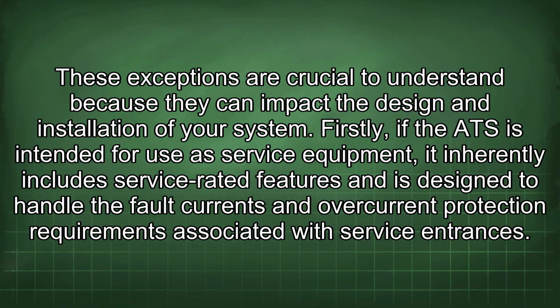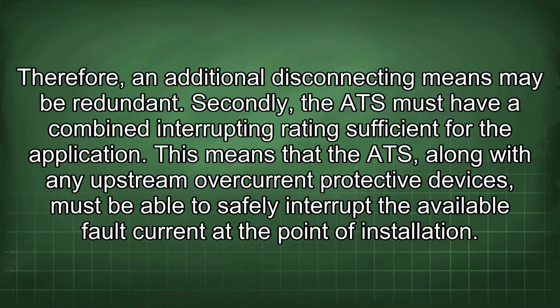Firstly, if the ATS is intended for use as service equipment, it inherently includes service-rated features and is designed to handle the fault currents and overcurrent protection requirements associated with service entrances. Therefore, an additional disconnecting means may be redundant.